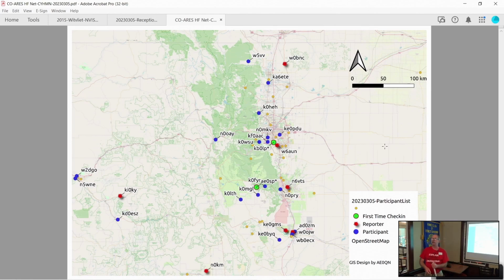Joe? Ham sticks. I haven't done this. Some people have. Take 2 ham sticks for like 40 meters or any of these bands. Mount them on a T horizontally from a vertical support off the ground. Did you try that? No, not yet. Darren, you were doing some, as NVIS. Okay, yeah. So that's an option.